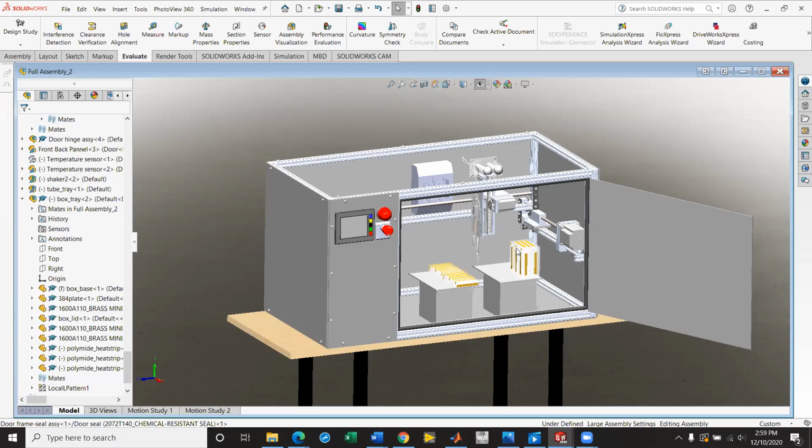Yeah, so actually, we did the heat transfer analysis in the preliminary design report. We set it up as a thermal circuit to determine the surface temperature, and we chose our high density polyethylene thickness based on that. It should be around 5 millimeters in thickness so that the outside of the device does not exceed 50 degrees Celsius, which is as per the customer needs.